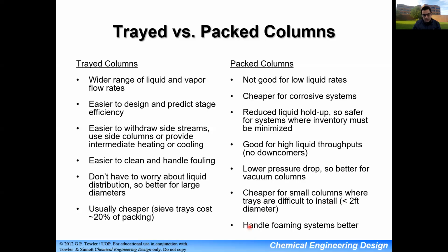However, as the column diameter increases, they become more expensive, and they're better at handling foaming systems, right? So sometimes in distillation columns, you get foam. You can add some additives to deal with this foam, but if you want to forget about these additives and just have a better system to deal with it, packed columns usually do the job.